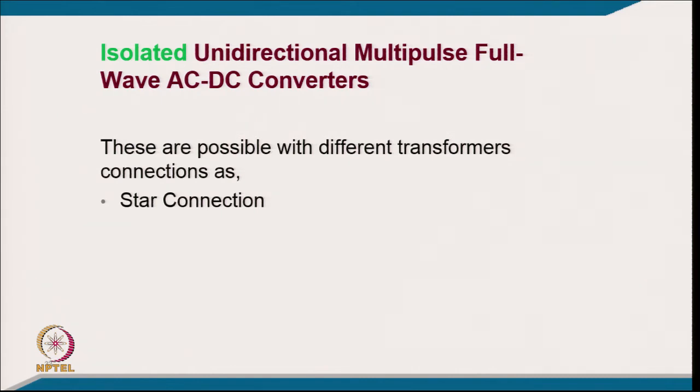The kind of transformer connection we normally prefer to use here: in full wave you require virtually a kind of return path, so we prefer all the transformer connections which can provide a facility of neutral, I mean a return path for the rectifier.